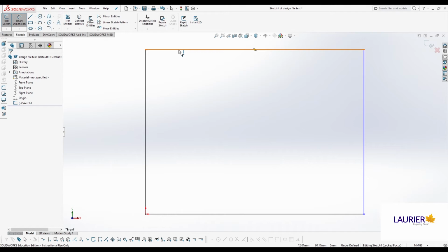In terms of CAD, it actually has a specific meaning. Now, I don't know if this is the correct technical definition, but this is a working definition that we use here in the Science Maker Lab, and it works really well to help people understand what an entity is in the CAD and what it does. If you can select it and only it, it's an entity. So an entity is the smallest individual item that you can select in a CAD. If you can select it without having to select something else, it's an entity. The flip side of this is we have to select entities to do any dimensioning.